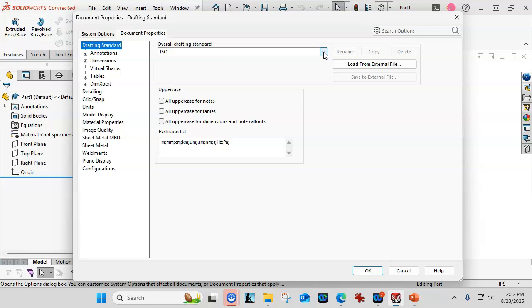A long time ago, I accepted the ISO, not thinking anything about it. I decided I liked some of the features of ISO, and I do largely generate my drawings in ISO. The main differences are that my vertical dimensions are vertical, whereas in ANSI they stay horizontal, even though the extension lines are vertical. So with ISO, the vertical dimensions align with the extension lines.